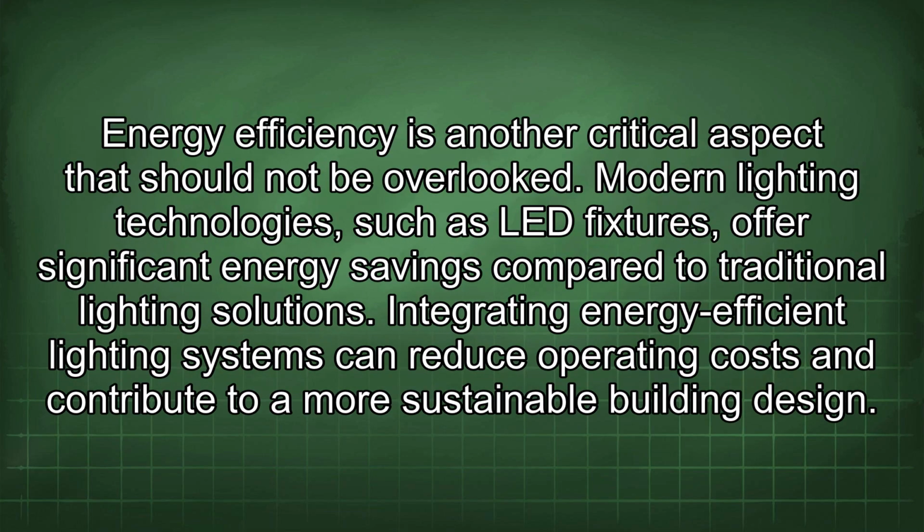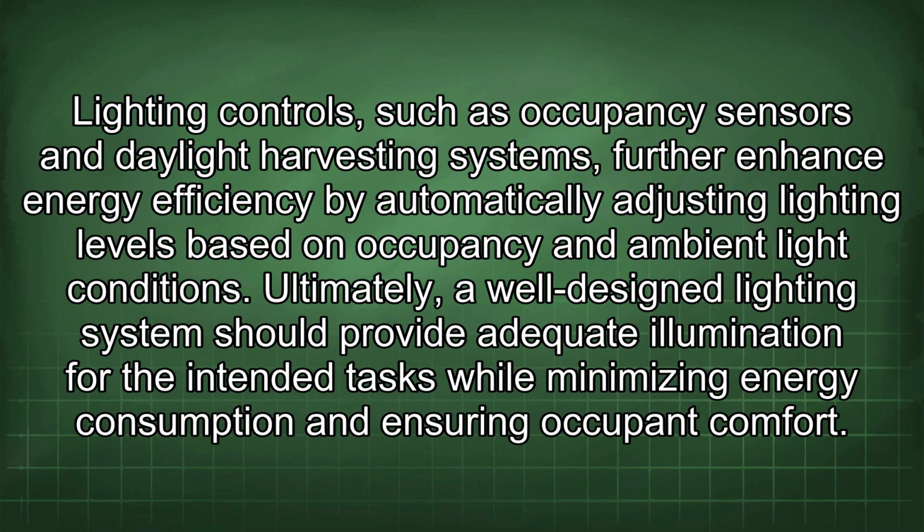Energy efficiency is another critical aspect that should not be overlooked. Modern lighting technologies, such as LED fixtures, offer significant energy savings compared to traditional lighting solutions. Integrating energy-efficient lighting systems can reduce operating costs and contribute to a more sustainable building design. Lighting controls, such as occupancy sensors and daylight harvesting systems, further enhance energy efficiency by automatically adjusting lighting levels based on occupancy and ambient light conditions.